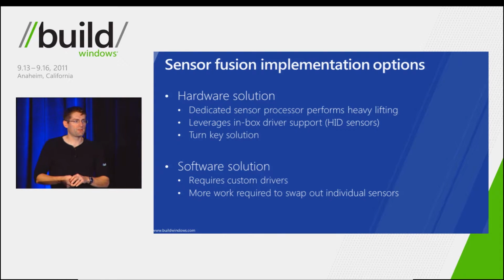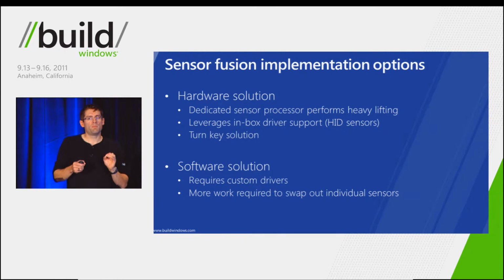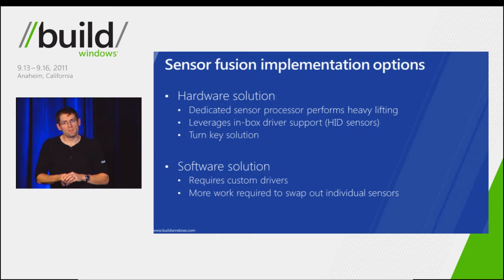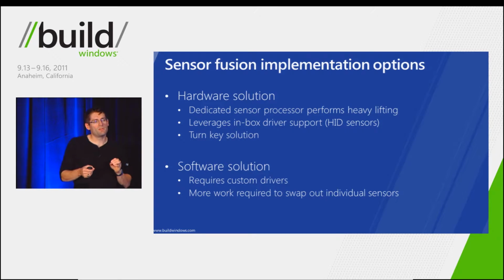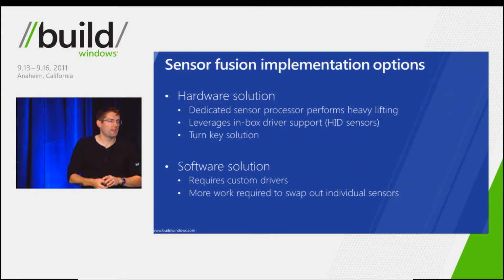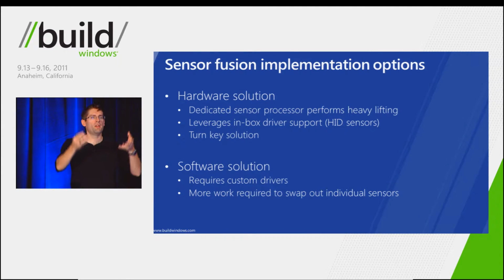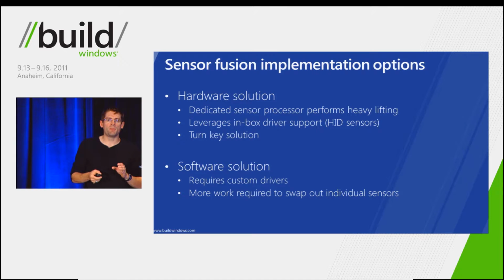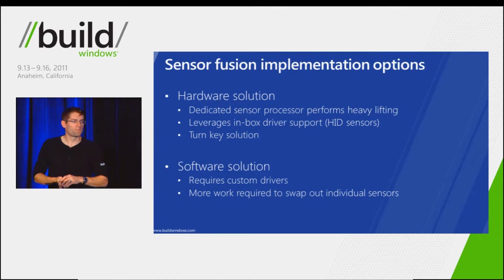So depending on the processor architecture, the power considerations, that kind of a thing, the software-based solution can also be an attractive solution. But if you are going to implement a software-based solution for sensor fusion, it's advisable to offload as much of the heavy lifting down onto the hardware if possible. So if you have a sensor component that has a DSP that can do some of the pre-processing on the data, your sensor driver can then just do the final fit and finish, integrate with the sensor platform, and pass the data more or less through with minimal power and performance degradation.